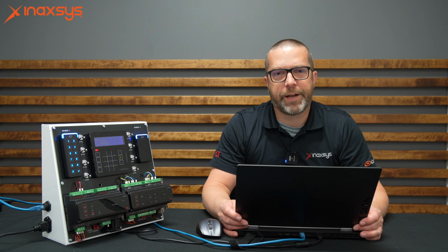So from the home page, there's a few steps. Basically, what we want to do is I'm going to be using zone 8 here on my kit to activate the keypad beeper to basically create like a door chime in the system. So basically the door opens and the keypad will beep to let somebody inside the area that someone is now inside. Okay, so the first thing you want to do is to create an input type.